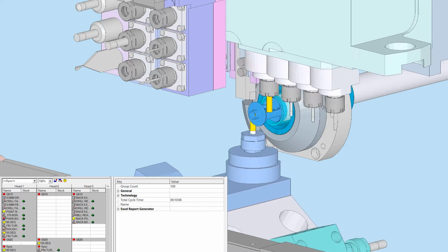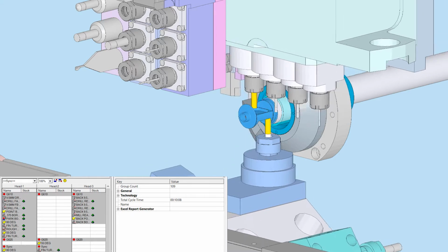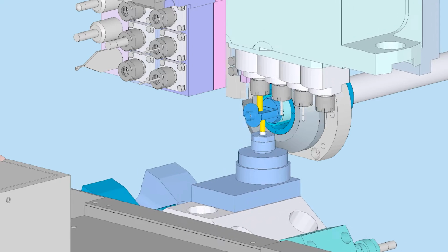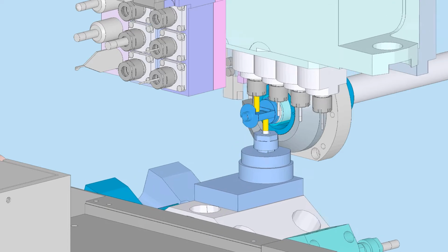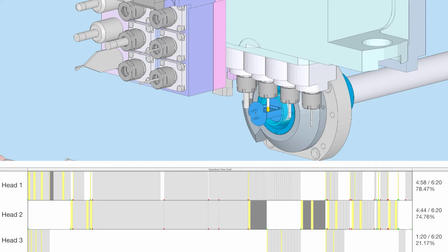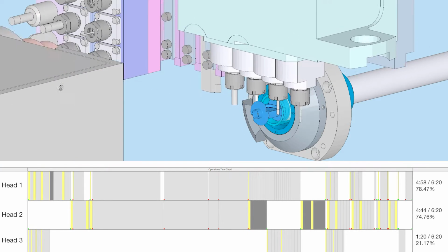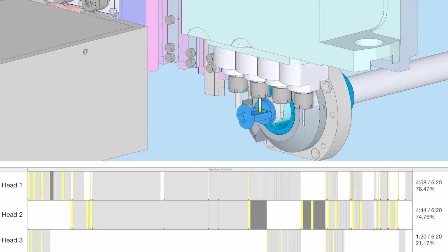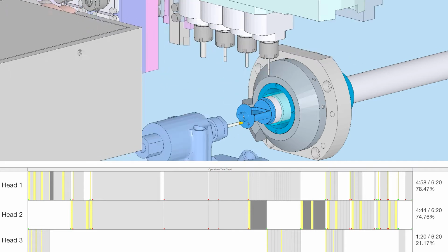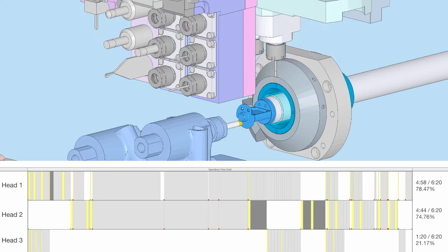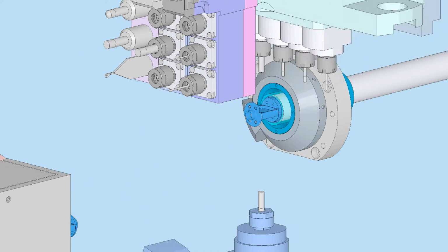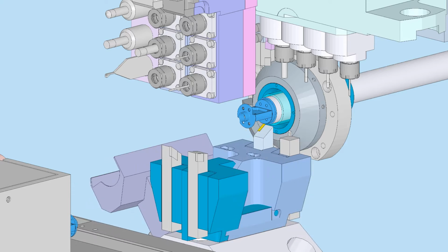What about reprogramming a part so it's processed backwards? Is there any room for improvement there? If you have good CAM, you can easily reprogram parts to be processed either way and see what is the best choice. And be confident that that is right. There is no guessing. There are only facts and verification. Cycle times can be more aggressive when you have a digital twin of your machine. If you know your clearances and you can see them on the screen with your own two eyes, you'll have the confidence to hit go out on the machine and not spend an entire shift single blocking code at 5% rapid, air cutting half the time.